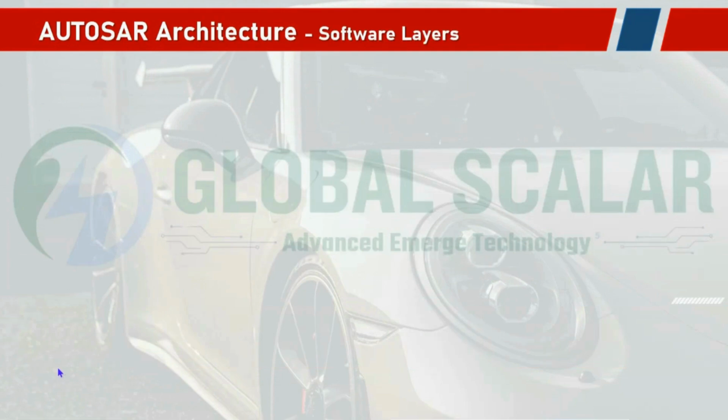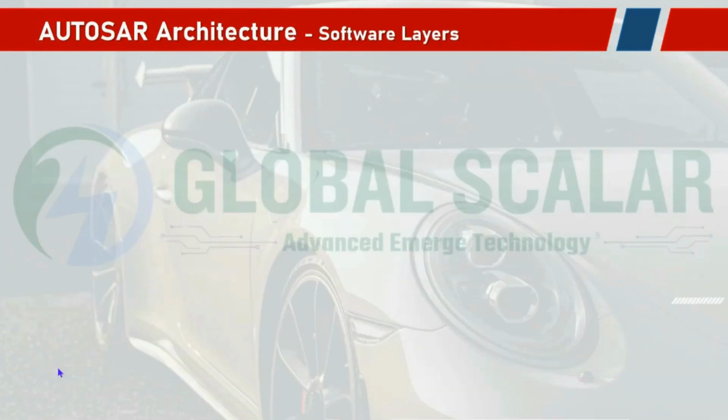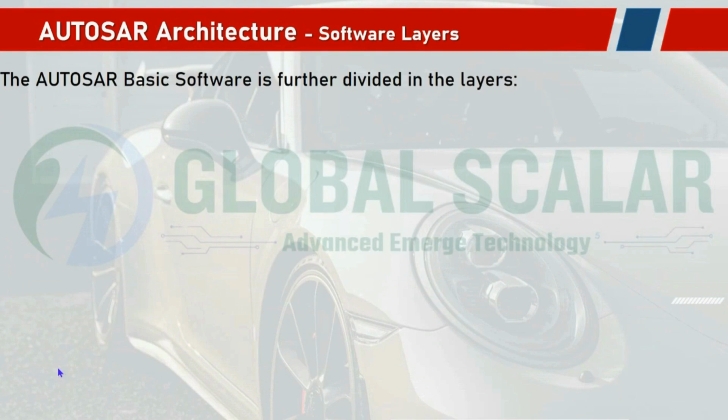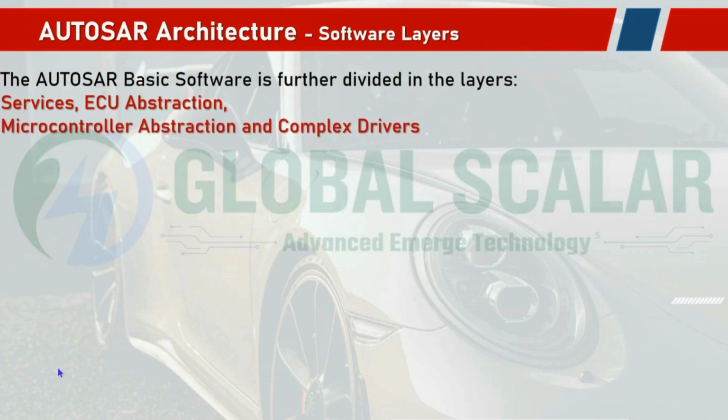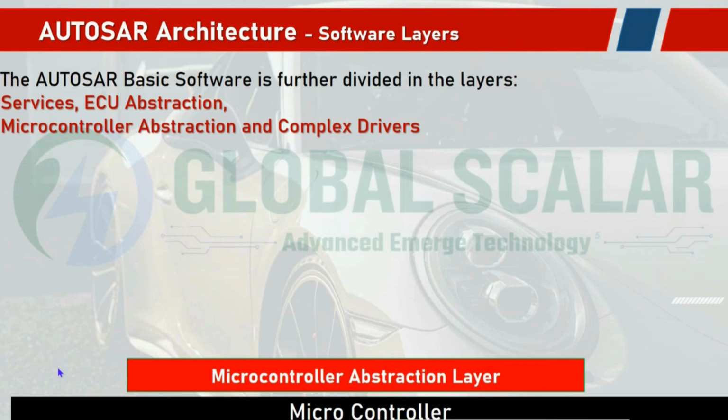We'll go into detail to understand the software layers. What are the software layers? How can they be configured? Here it is divided into services, ECU abstraction, microcontroller abstraction, and complex drivers. These are the software layers we are going to discuss in the architecture. The main focus is the microcontroller. The microcontroller here is the hardware resource, and on top of that we have the microcontroller abstraction layer.